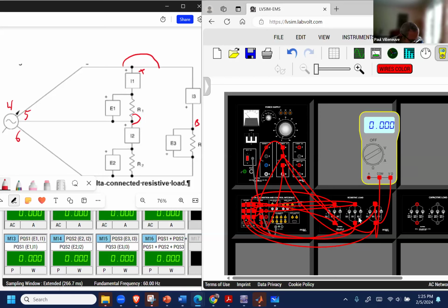If you look at the 300 ohm resistor, what's the rating on the 300 ohm resistor in terms of its current? Anybody read that? I can't read it on my screen, but hopefully you can zoom in on yours while you're building your own circuits. Is it 0.4 amps? Very good. It's 0.4 amps. What is 120 divided by 300? It's 0.4 amps, right? So the reason why I don't want to drive this more than 120 volts is I don't want to exceed the capacity of these resistors.